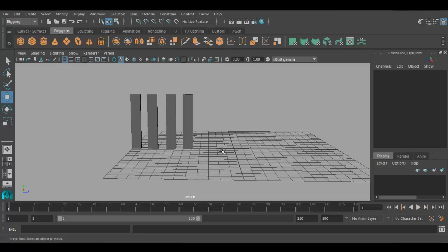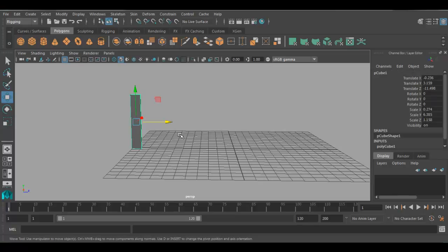The next option which we will see is Duplicate with Offset. Duplicate with Offset is used to execute the duplicate command with the same offset. Let us see how it works. Before executing Duplicate with Offset command, first you need to select the surface. Choose Translation tool.